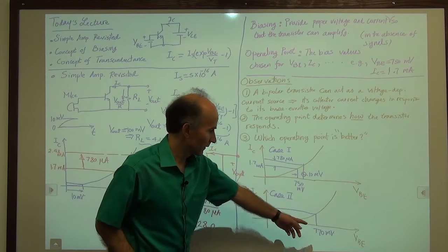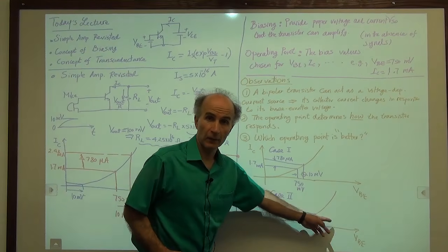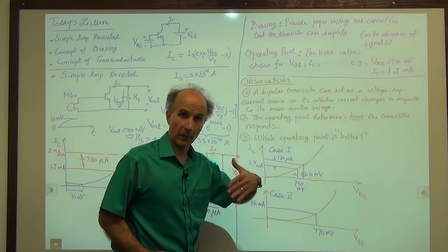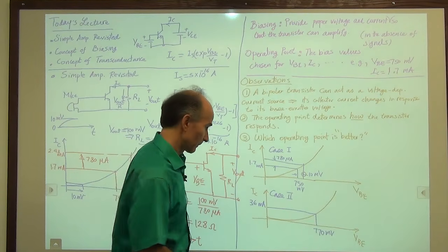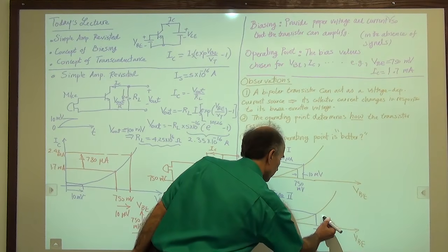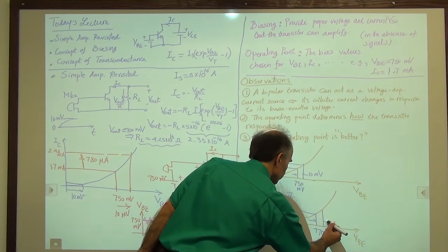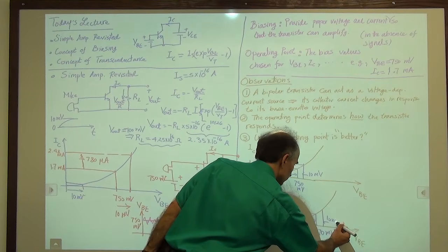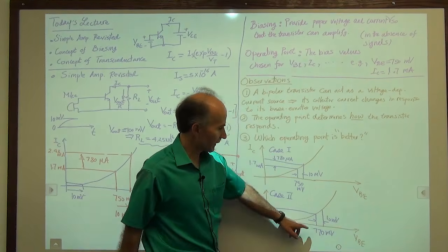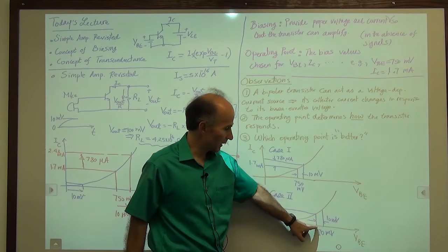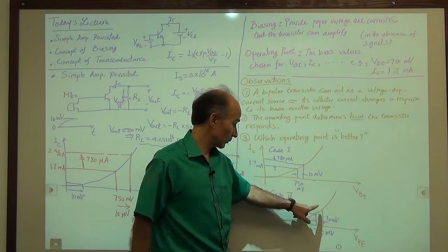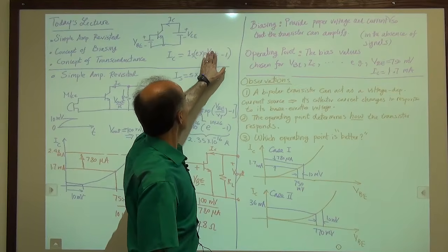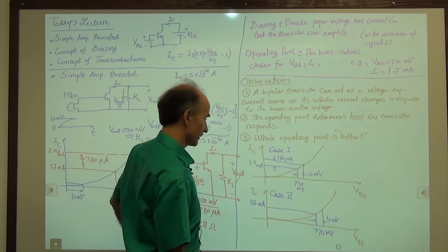How about here? If I increase this by 10 millivolts, again assuming that the signal from the microphone is added to this 770, then what happens? So the microphone signal brings the VBE from 770 to 780. How much current do we get? Well, plug in 780 here. We have IS, we can find IC.